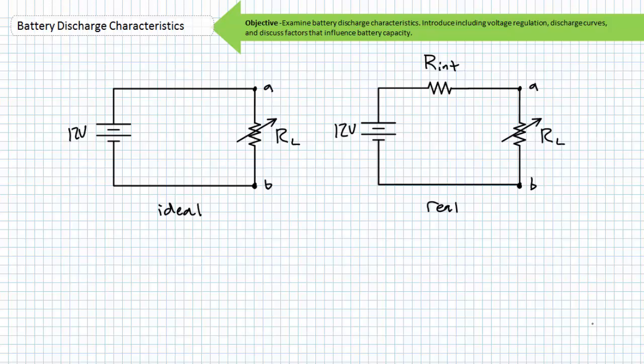For the purposes of this lecture, we'll assume the internal resistance is constant, but be aware, the varying ionic resistance changes at the extreme limits of discharge. Those with an understanding of basic series properties can already see how an additional resistor in series with our electrical load can change the observable electrical properties for varying load conditions.